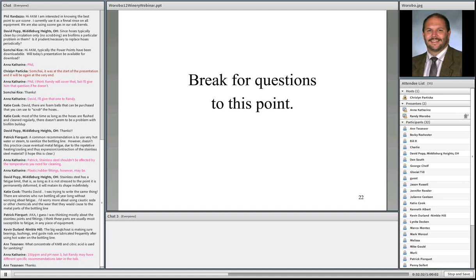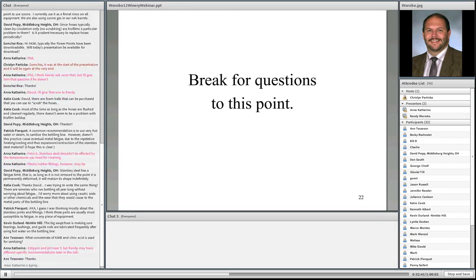Some people will actually boil their hoses, and within the first day they've already got very high levels. Swabbing results of rubber hoses that have been treated with citric SO2 show that it does not improve the sanitation. They're very difficult to treat. One of the better suggestions is Tygon corrugated hoses. They're not as flexible and a little bit more expensive, but they're opaque, so you can see if there's standing wine, and you can also see how good of a job your cleaner is doing.